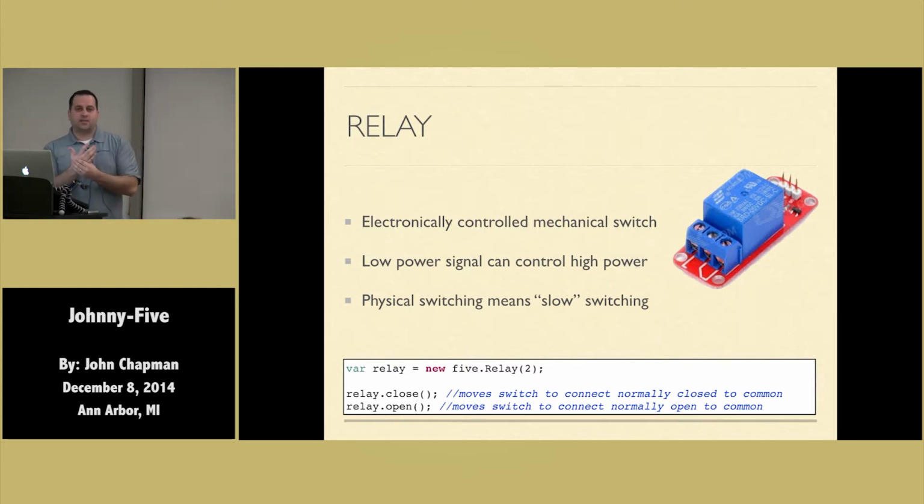We're also using a second relay to simulate button presses. So inside of his hand, if you squeeze the Mickey hand, there's a little button in there that basically connects two wires. So instead of using a hand, what I've done is I've also used another relay that whenever you turn the relay on, it'll connect those two wires together, simulating a button press inside of the Mickey.